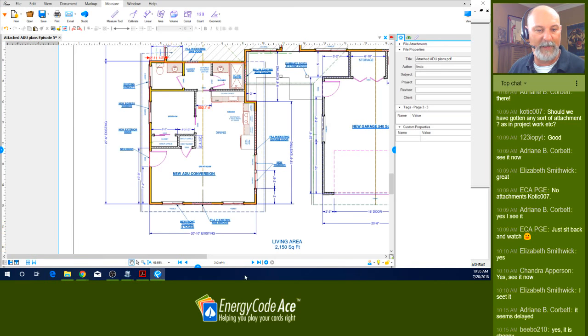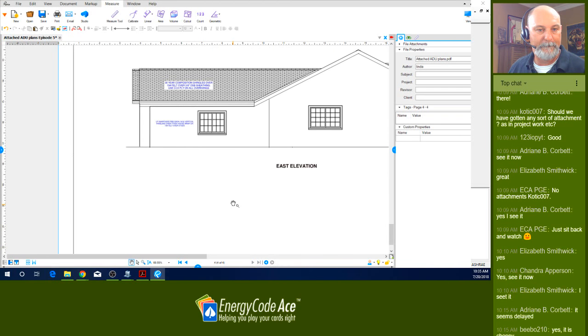I can't remember what that was. So we had a question in the chat. Somebody was asking if we went with above roof deck insulation, would they need new roofing? Yes, they would. Now, keep in mind, because this is an addition, that existing roof is considered as a new surface.